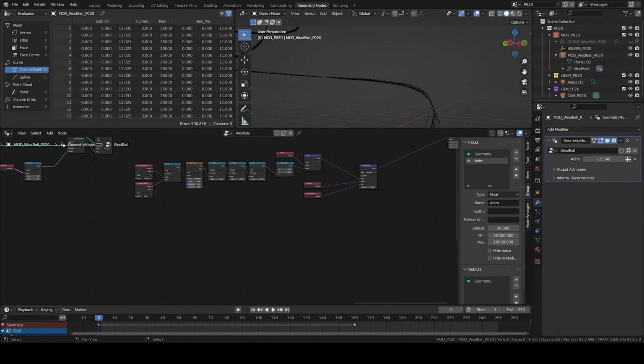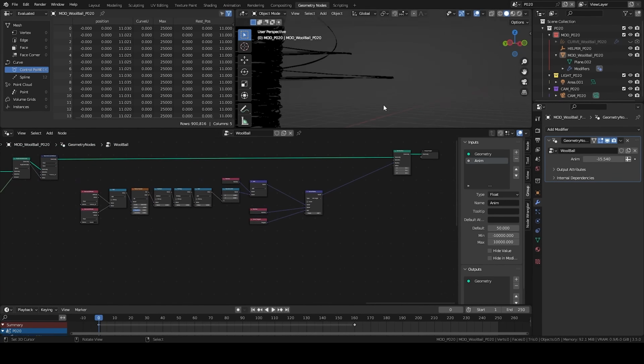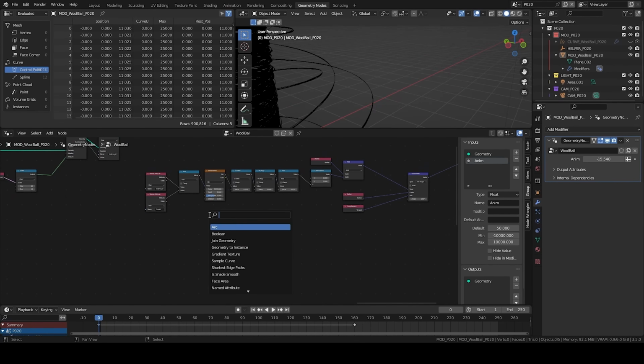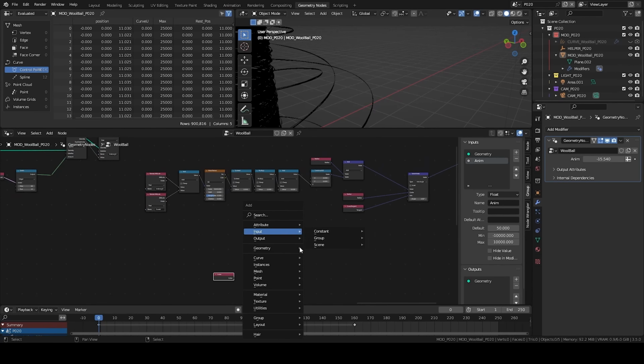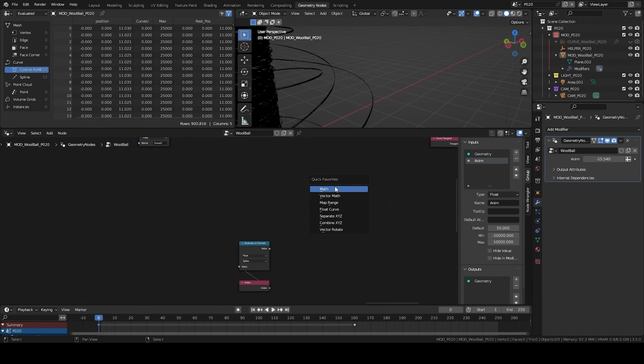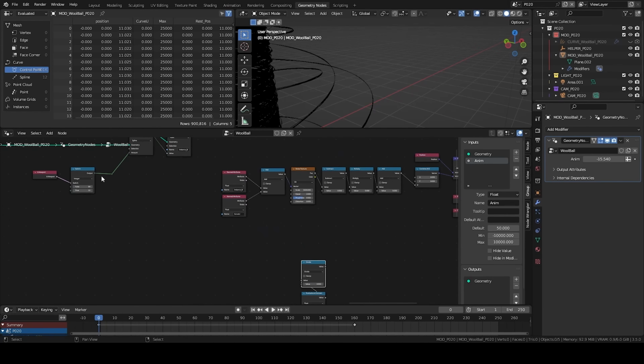And here, we're going to create coordinates that allow us to rotate the curve over its total length. So I'm creating an index node. Evaluate on domain. It works on the splines. Divide by the total number of splines available. I put in the first entry, and in fact, it's this value that's going to come in the second input of the divide.